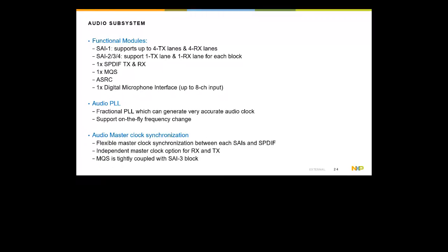So not only does it reduce cost in your BOM, but it actually includes a hardware voice activity detection module, meaning you can provide a wake up for, say, the M7 core upon hearing some sort of human voice activity proximal to the device.